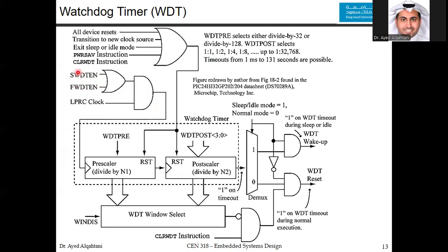Now, in the software, if you disable, making this 0, and this is also 0, then the value here is 0. If it is 0, then whatever you are having here, it will generate 0. It's static, never changes. The watchdog timer's beating heart won't start. Nothing happens. That's the idea here. You see what's written here for the watchdog timer prescaler and postscaler, but we will discuss them in the next slide in a better way.